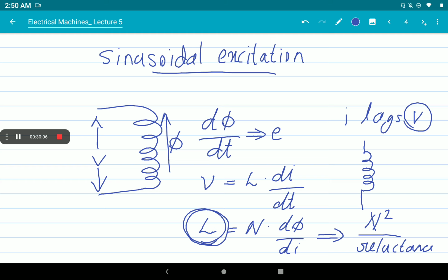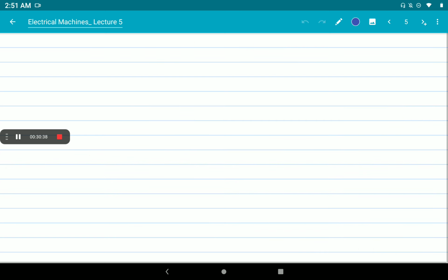And also in the magnetic core we have studied two types of losses, hysteresis loss and eddy current loss. Usually in an electrical circuit, the losses are represented by resistors, and we are taking both of these in a parallel connection. So we usually represent the magnetic material or magnetic circuit as a resistor in parallel with the inductor coil. I will again explain.